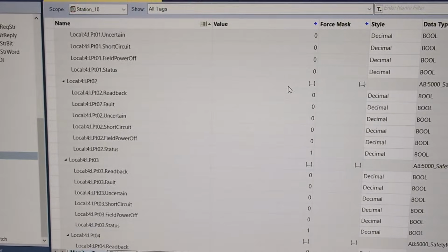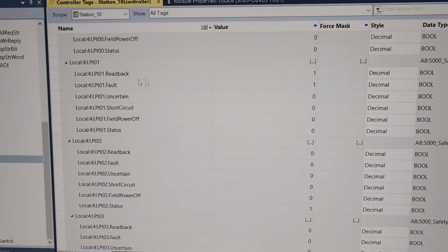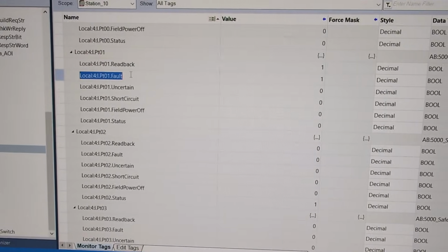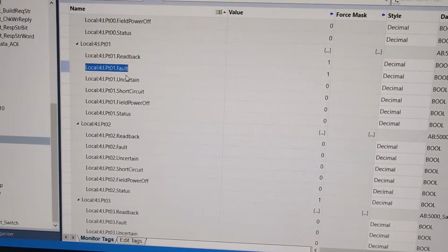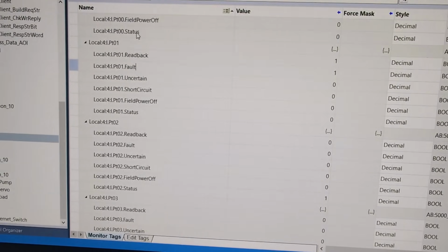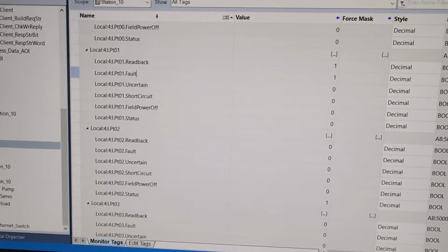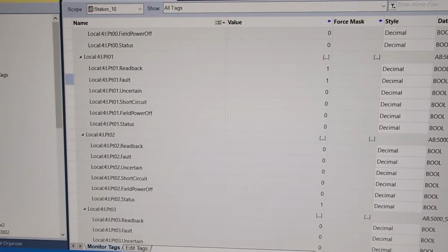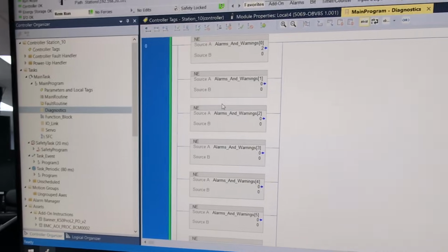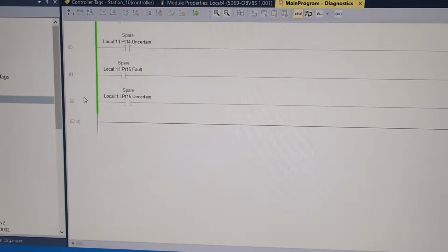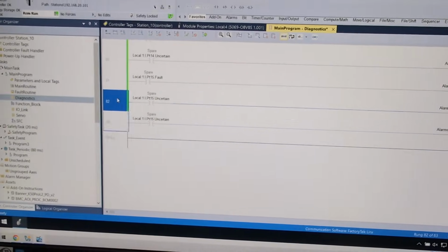So now here's where the question is, how complicated do you make your diagnostics? I'm not sure. Is the fault good enough? I don't think we could think through all the combinations. I think knowing we have a fault on output 0 or 1 would be good enough to start with. So I'm going to add those to that fault code we did yesterday, and we're going to see how we would work through it. I'm going to go down over here to diagnostics, and way down here to where we ended yesterday's video, and do that fine copy and pasting thing.